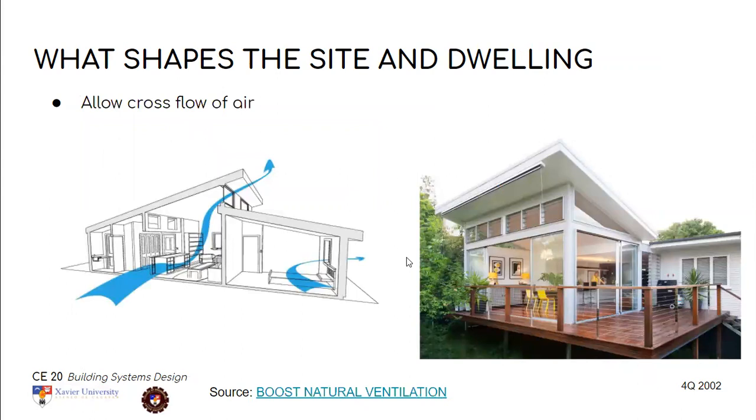The design of the house of allowing cross flow of air is also important. This is why houses with semi-flat roof are ideal, as this allows louvre design on the wall where winds can flow out instead of in, and proper passive lighting is also accommodated.